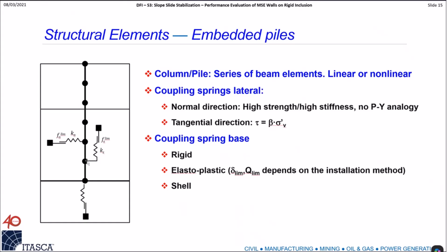And then you convert to the tau so that you can limit it. So if you have a relative movement of the pile that goes over, essentially, if you mobilize the full capacity, at some point the force does not increase, so the tau does not increase anymore at that elevation, especially close to the top, in case you have a high axial force.